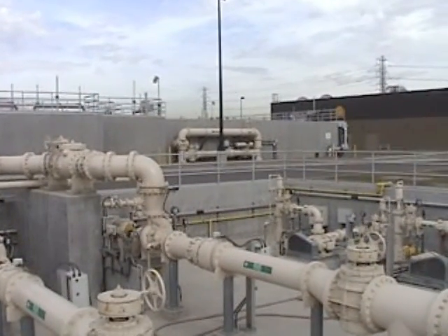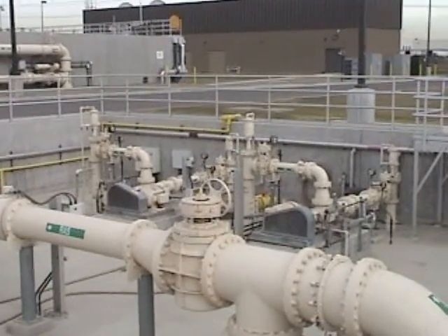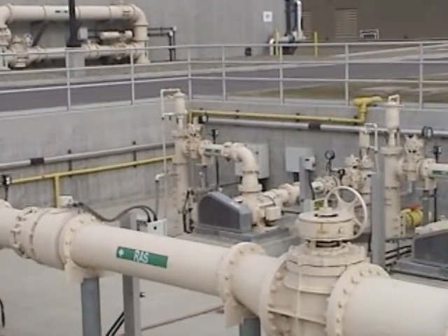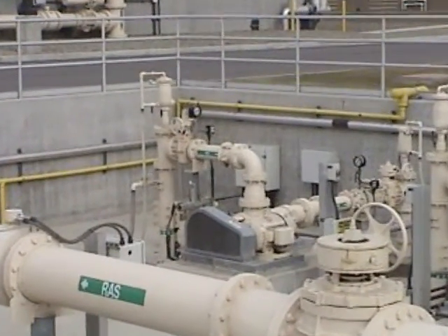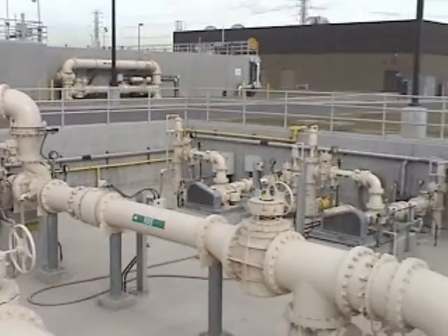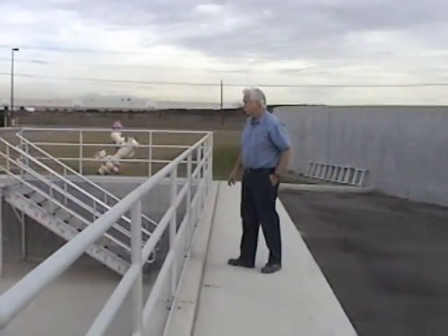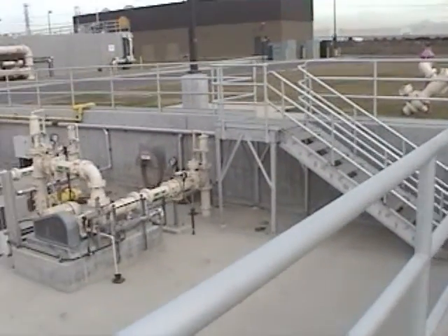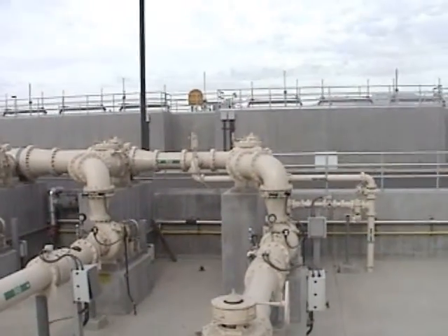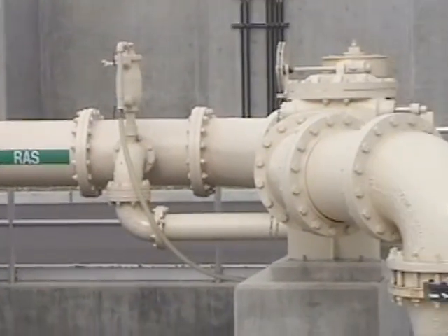The 2 smaller pumps over there are WAS pumps, and we only have the ability to waste RAS at this plant, and those are the 2 pumps that do it. If we walk over here, I'll show you where they pull off the header. You can see that the WAS pump is right there, and then over there where it says RAS, just to the right of that, you see that pipe right there? That is where we pull off RAS to be pumped out of the system.